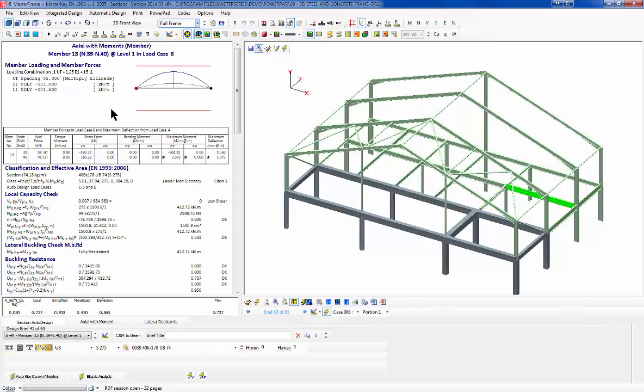This one, we have quite a lot of bending moment on it. It's just been, the convention has just been changed to draw it upside down. I'll leave that at the moment. I haven't time to go and correct that. And I can see that we're quite close and we have a 74% unity value.